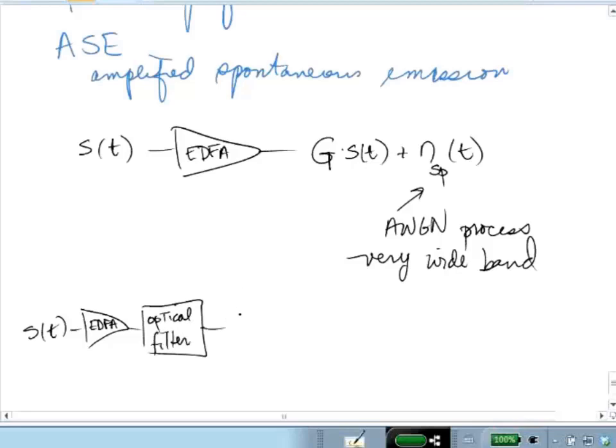of that process. Then we'll go through the photodetection, and of course the photodetector also adds wideband noise, and so we're putting here an electrical filter in order to limit the effects of the electrical noises introduced by the optoelectric conversion.